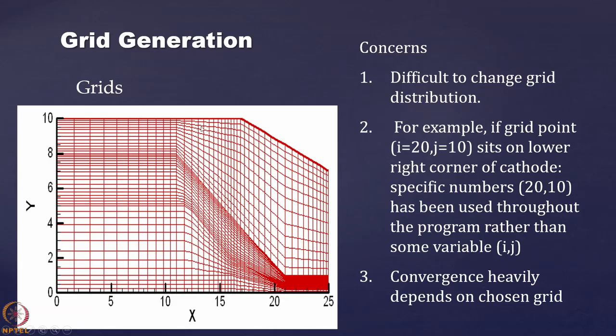Once you do that, and this is the grid generation. This grid generation is very simple. It's a finite volume grid, and you can see that the grids are not uniform. We have used a non-uniform grid. There are zones where the things are varying very rapidly. At those zones, we need to place the grid points very close to each other. Whereas where the parameters are not varying significantly, we can keep a coarse grid like this one. Okay. But here the things are changing rapidly, so we need to capture those physics. So we need to keep a denser grid over this zone.